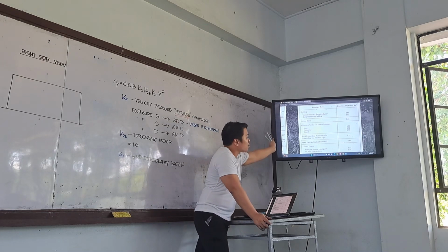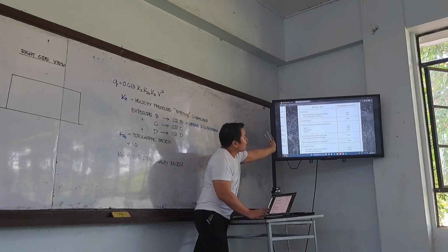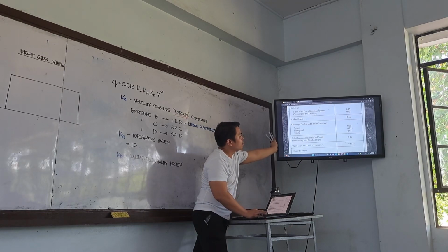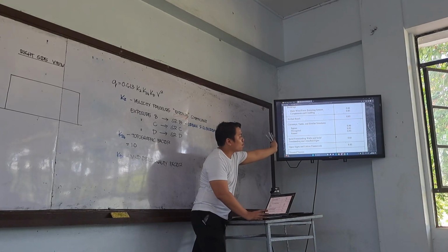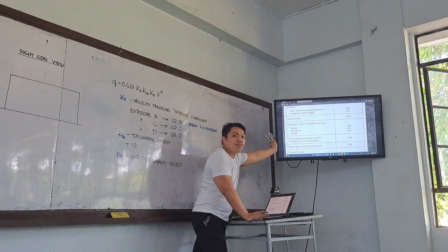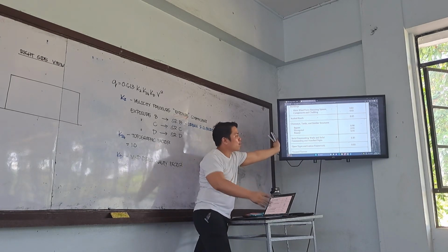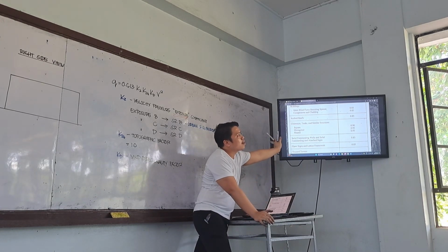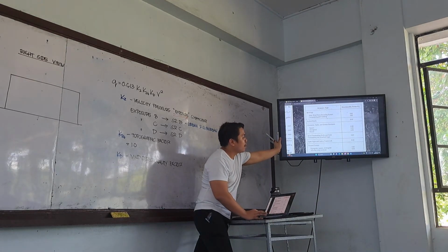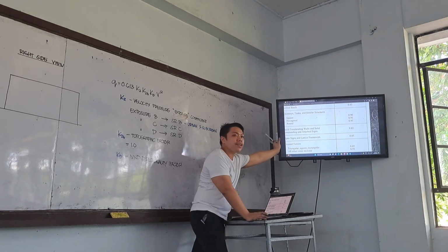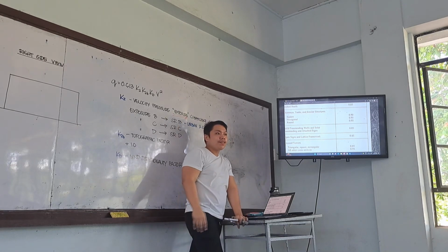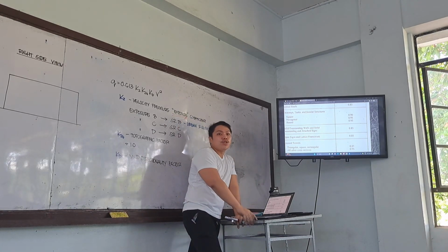For our truss towers, it is about 0.85. But for chimneys and tanks, why do you think it is higher? For round shapes it is 0.95. The wind has nothing to flow around, so the structure resists almost 100% compared to your buildings. Sir, why are truss towers 0.85? Truss towers are open, so the wind flows through. No, your members will still resist the wind.